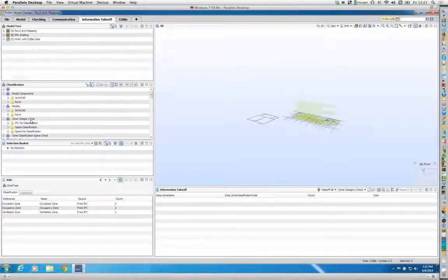But they haven't connected it to the IFC-based export. So what it's used for is just generating the Excel-based output. If they connect it up to the IFC side, then we don't have to do this part either, because it means they'll export true IFC classifications as well. But in this case, they're not doing that in the same way.